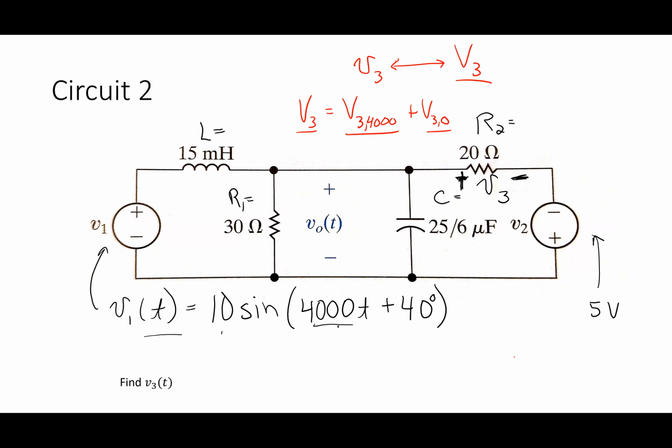So it's like I'm asking you to find the steady state result in one of those differential equation problems. Because when I do impedance, I'm doing steady state, right? So what's that mean about the capacitor and the inductor? Do I even need to put them into my analysis? No. In fact, it's kind of weird. If you actually went into MATLAB and you said Z sub C equals 1/0 times C, I'm not really sure how it's going to react to that. It's probably going to say inf, right? So it's probably not a wise thing. So I actually would make the simplification to say, I know there's no current going through the capacitor.